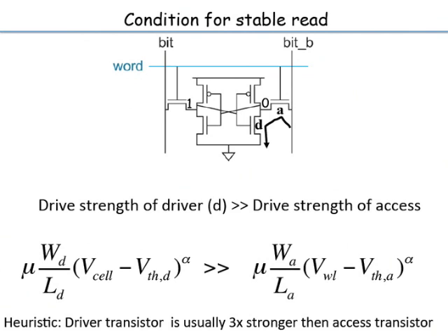Every time you break the memory, say instead of having 1024 by 1024, you say I'm going to have two pieces, 512 by 512. You have broken the memory horizontally and there are two rectangular slabs now. You have to have additional circuitry for each slab. So you start increasing area overhead. As you start partitioning and making smaller and smaller memory subarrays, you will increase partitioning area overhead. Overall area goes up. So again, there is an optimum for how much you should partition.